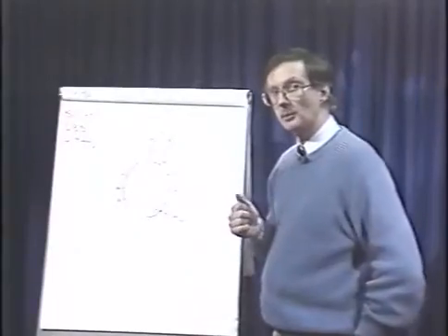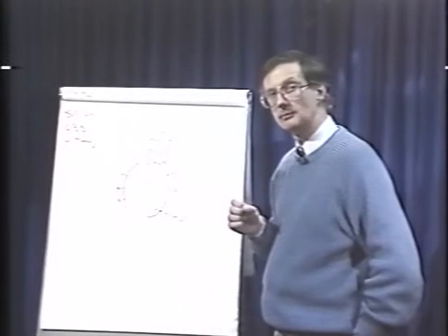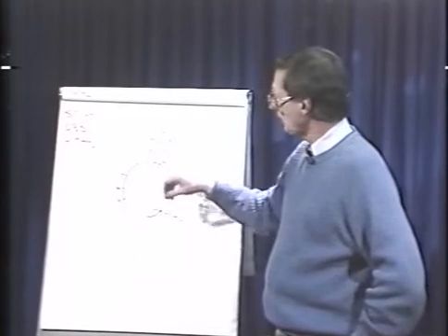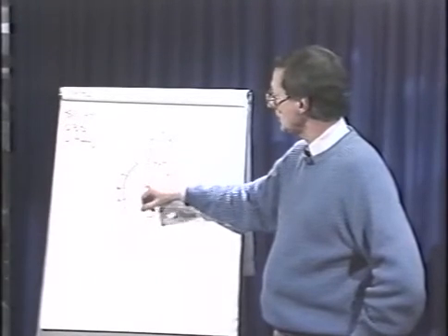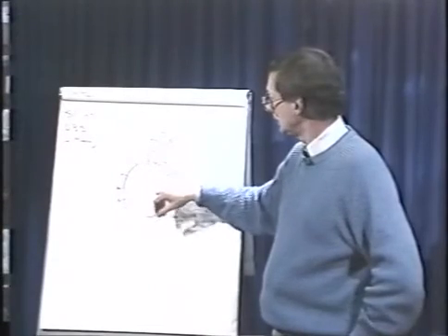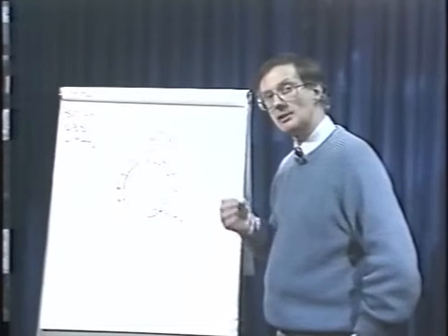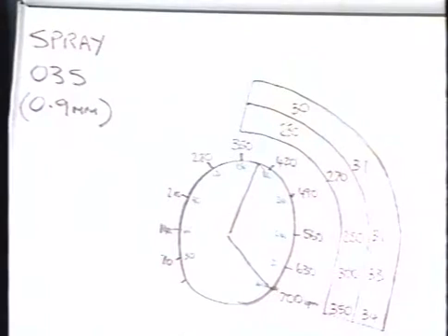The selection of parameters for spray transfer is relatively simple. Do you remember with the 035 wire where we finished the short circuit welding at the 1 o'clock position, around 200 amps? Well, to get spray and to get into that high deposition process, we have to be over 200 amps.